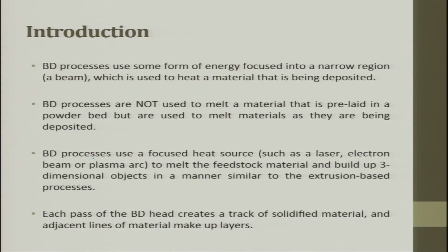Beam deposition processes use a focused heat source such as a laser, electron beam, or plasma arc to melt the feedstock material. The feedstock material, a wire here, is used to build up a three-dimensional object in a manner similar to extrusion based processes. Each pass of the beam delivery head creates a track of solidified material, and adjacent lines of material make up the layer.